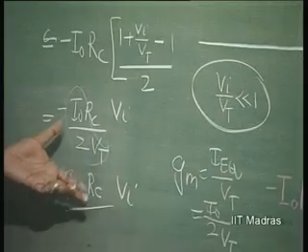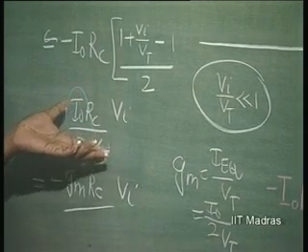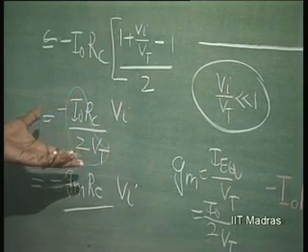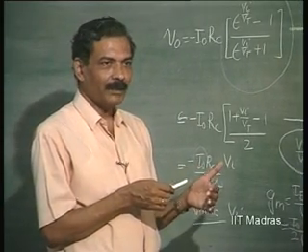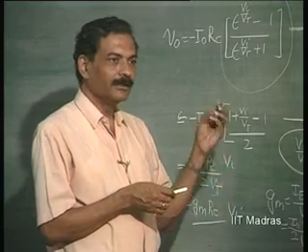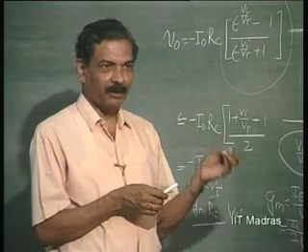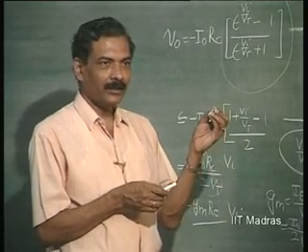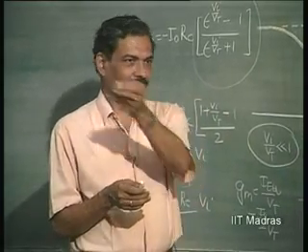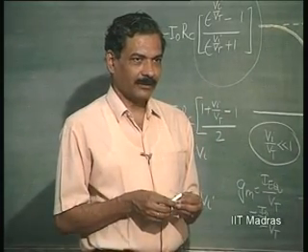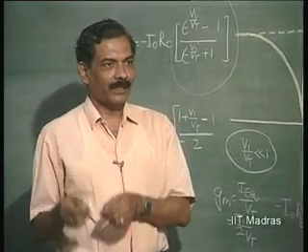So, you will see that as far as the differential amplifier is concerned, the nonlinearities will be less than the nonlinearities in the common emitter amplifier, where you have what kind of nonlinearity? Exponential nonlinearity. That means e to power x is 1 plus x plus x squared by 2 factorial, and so on. So, all the terms exist. After x you have x squared by factorial 2.